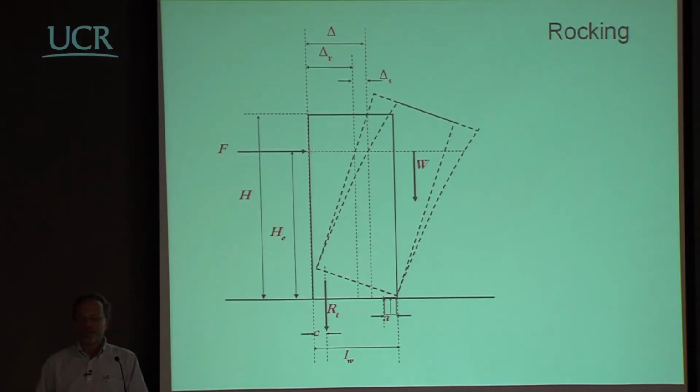Rocking is certainly a kind of natural way of isolating a structure. I've already discussed rocking, because when I was talking about the out-of-plane response of a masonry infill, I was exactly talking about rocking. If you want to see what happens in the simple case of a block like this, it was a problem discussed by Housner in '56, and then Nigel wrote a paper on the damping that you can obtain due to the impact on the ground and so on.